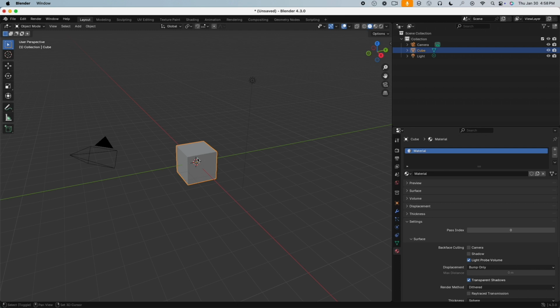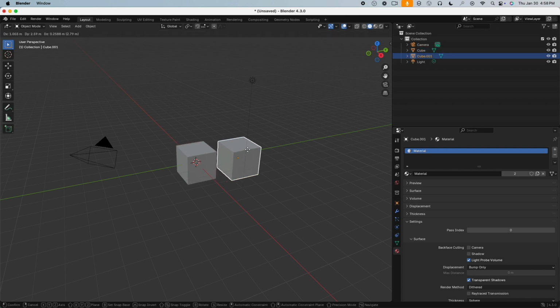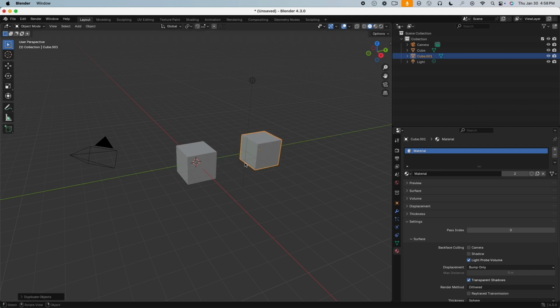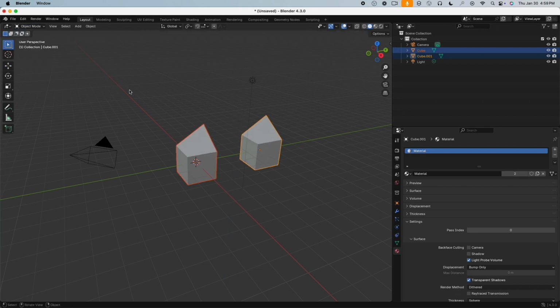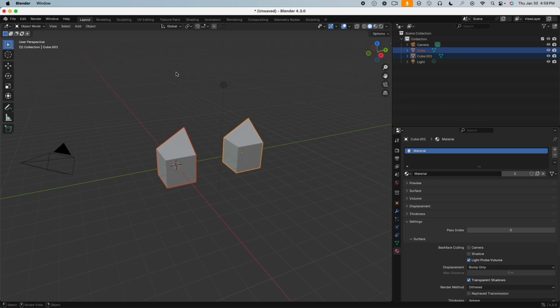One actually quick demo: I press Shift D, G to move, and Y. With Shift and left mouse button, I select both. I go into edit mode, and I can move the points of these two cubes in both objects. Something you can't do in SketchUp. Anyway, there's everything on how to use it. I will explain more also in the individual tutorial, so you don't have to just memorize everything right now.